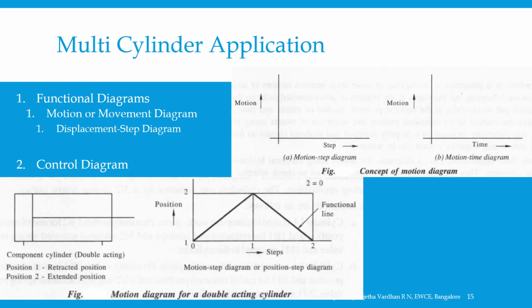If the condition of the system changes during the motion of the element, that is, by operating a limit switch while the component is in mid position or due to a change in the advancing speed, intermediate steps may be introduced. The steps may be numbered as required, and the designation of the condition of the component is optional. The designation of the component must be written on the left hand side of the diagram, for instance, like cylinder 1.